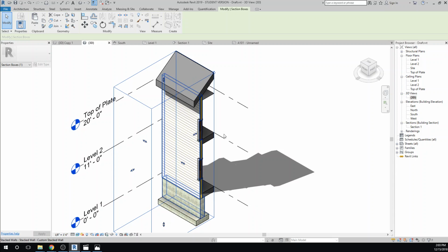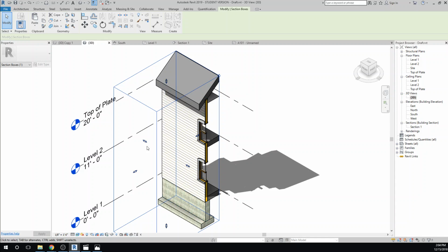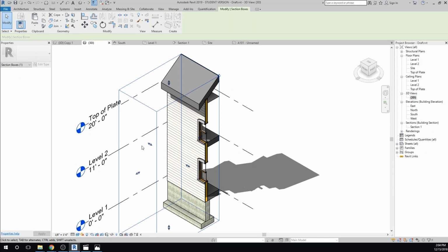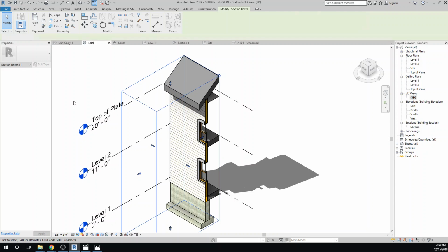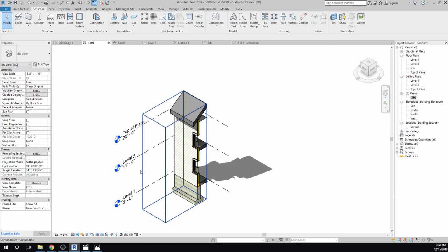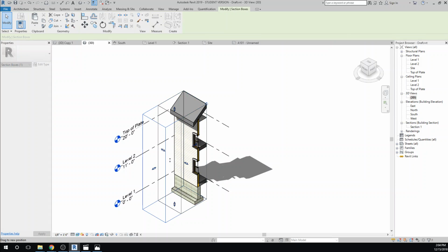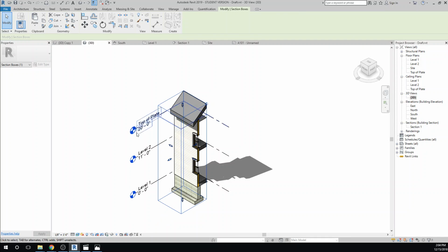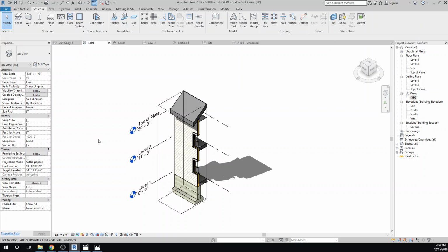And we have a little more window we probably would like to show, and a little less of the rest of the house. And that gives us a pretty good crop. And I'll bring this one in because that'll bring those section lines in tighter too. So there we have it, and I can tell that already our scale is too large, so let's go ahead and change our scale on this drawing. And we'll try to see if it matches with the other one. We'll go to 3/4.